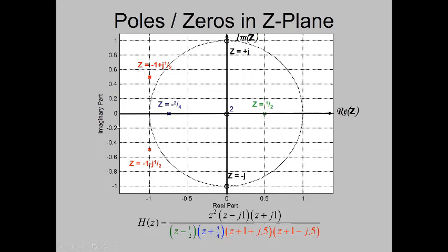And this would be the pole zero diagram for the system. And it turns out those pole and zero locations will determine the dynamic behavior of the system, because from those, we will get back the difference equation coefficients. If we recombine these different factors into a polynomial, we would have the a_ks and b_ks of the difference equation.